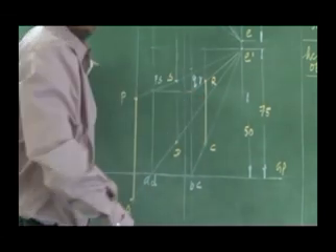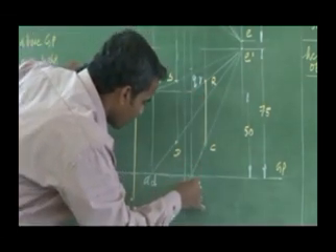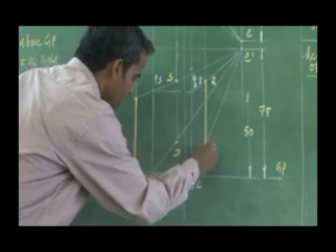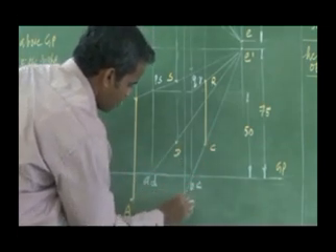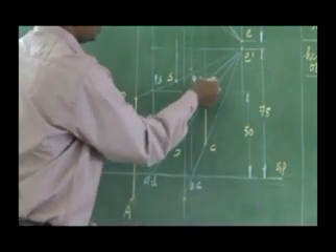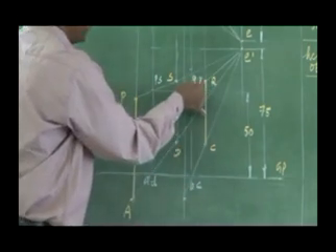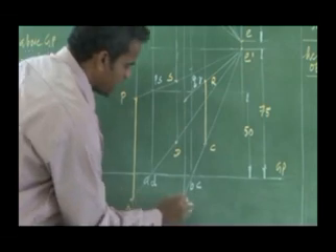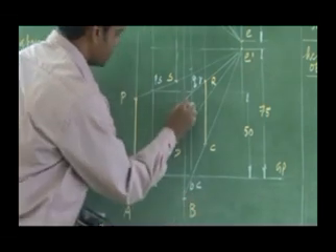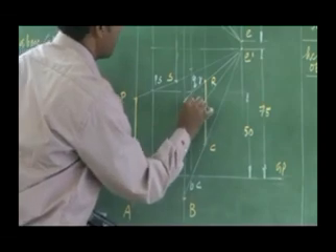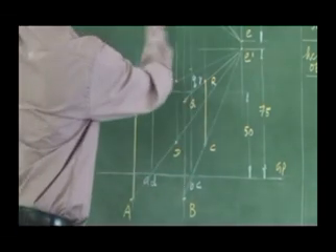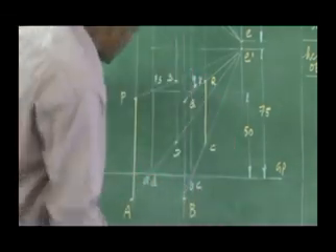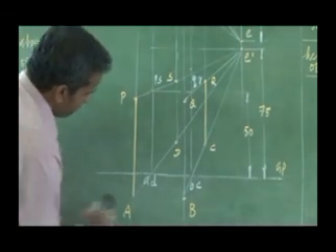In the same manner, I have to extend B so that I get it on the same location. Q I have to extend in the same manner. So that is going to be my B. This is my Q. Now this face APBQ will be an enlarged face in my perspective. Join this APBQ in sequence.